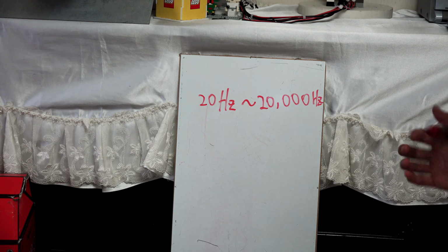So it measures how long the high continues. When the high goes down, it returns the duration of how long the high is, in microseconds. So yes, this is how we get the duration from the ultrasonic sensor.